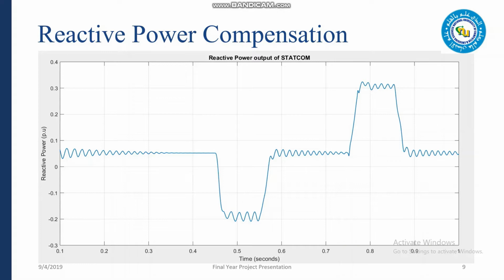During this second transient, we face an overvoltage condition from 0.75 seconds to 0.85. Our device rectified this by delivering reactive power back into the grid. With these graphs, we can prove that our STATCOM simulation does exactly what we designed it to do. It regulates voltages through reactive power compensation. The maximum compensation it can provide is 6.7 MVA, roughly 0.3 pu of the rated power of the system.